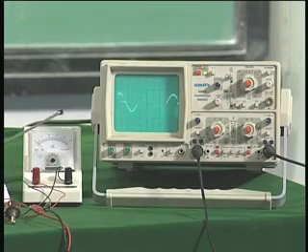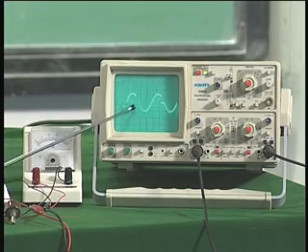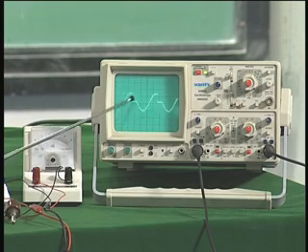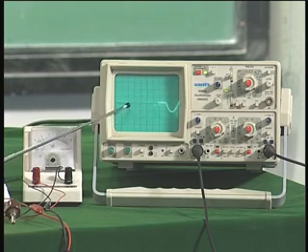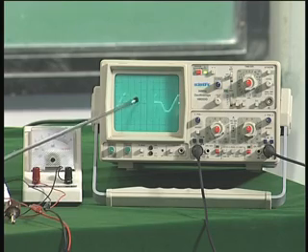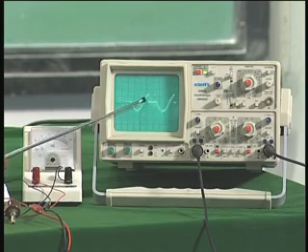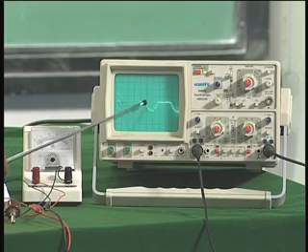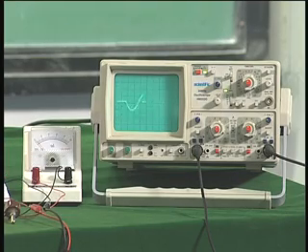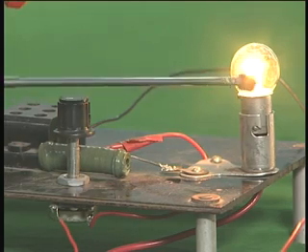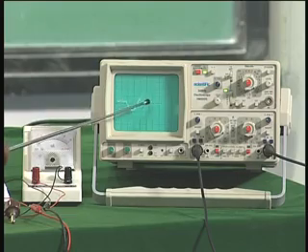Now you can see, if I increase the potentiometer, you would find the horizontal portion increases. That means it is now triggered almost at 90 degrees. Now, it is beyond 90 degrees. Now, you see, this amount is across the SCR, the rest of the voltage is applied across the load. Therefore, that should correspond to a very bright lamp. So, now you can see the lamp is very bright here also. So, this corresponds to this signal.